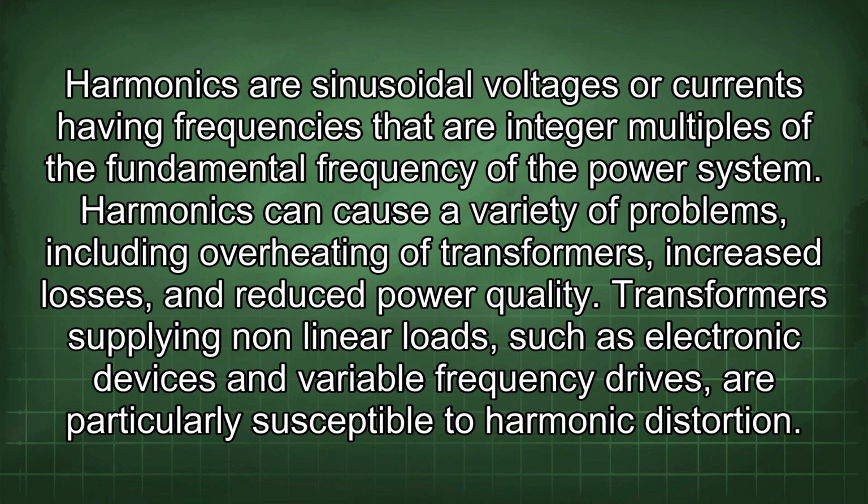Harmonics are sinusoidal voltages or currents having frequencies that are integer multiples of the fundamental frequency of the power system. Harmonics can cause a variety of problems, including overheating of transformers, increased losses, and reduced power quality. Transformers supplying nonlinear loads, such as electronic devices and variable frequency drives, are particularly susceptible to harmonic distortion.